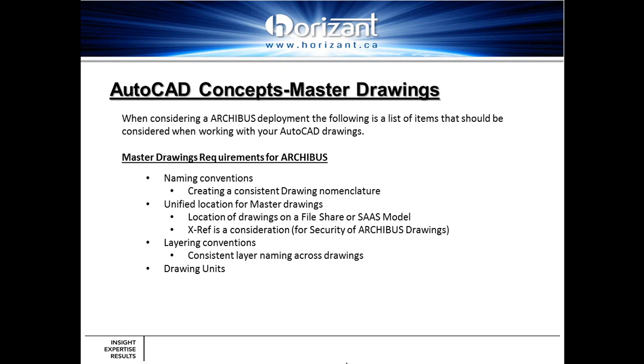ARCHIBUS will then also have the ability to drop in blocks and scale the blocks between one drawing and the next. So if you take an imperial block and drop it into a metric drawing, it will convert it and scale it accordingly for you. So those are the sort of things we want to be concerned with within the corresponding master drawings.